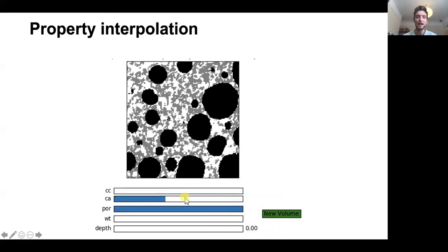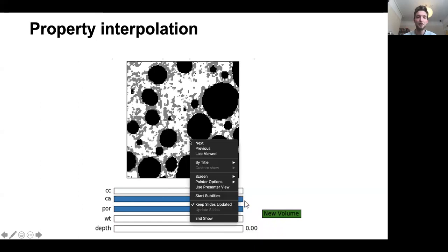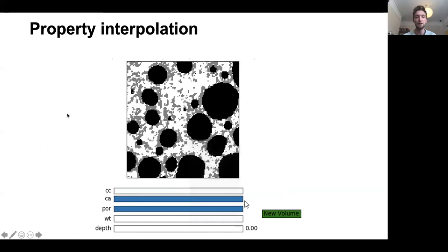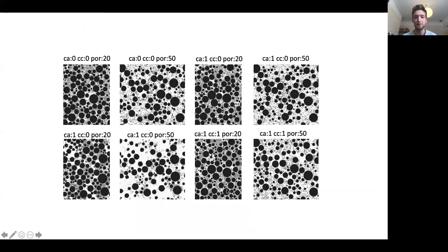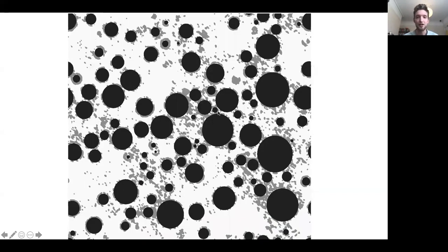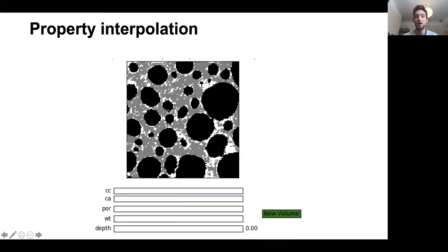As we increase that, in this final image suddenly we have this cohesion of binder around our NMC particles, where the binder tends to stick, and that's realistic. If we compare that to these training images, you can see that the high binder caused exactly this to happen, but the nice thing is we can interpolate all the possible structures in between.